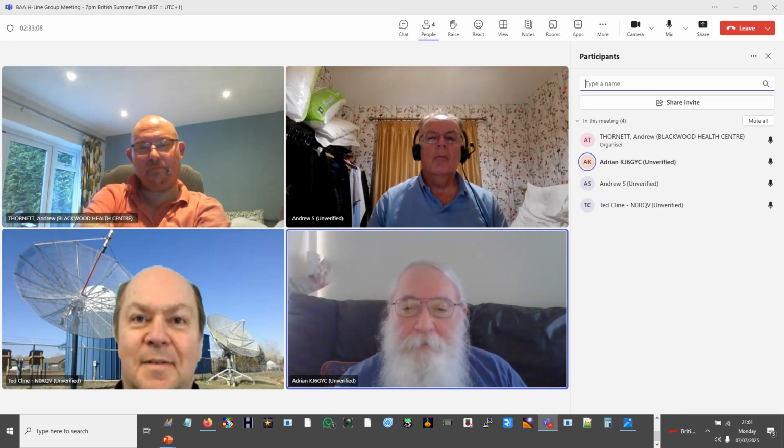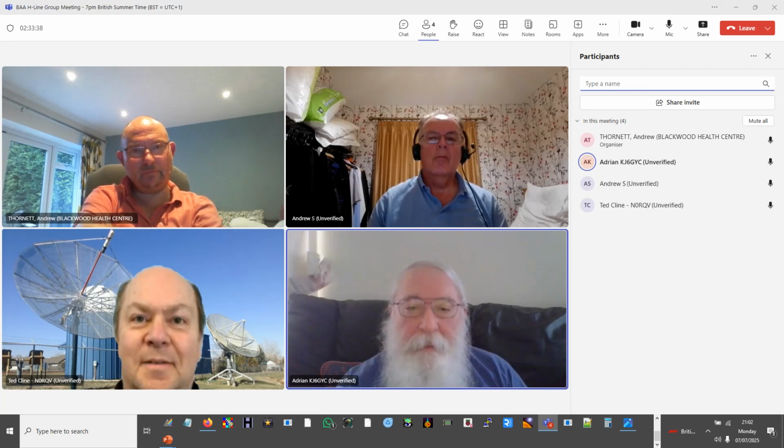Buy yourself a handful of the chip. It's kind of the old standby, called the 7805. It's a positive voltage regulator that you feed the 12 volts. You put a couple of capacitors on one side, input and output, and you get out a nice clean 5-volt supply to power all the LNBs and so forth. No spikes on it. It's not going to have any of the harmonics from the switching circuitry and whatnot. That's what I would do. That's what I would use.